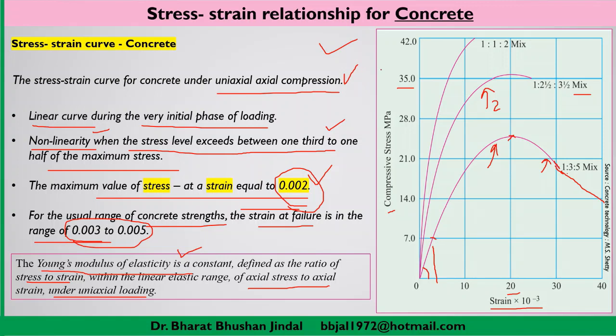So that means you are applying the load on the cube of the concrete just for 5 to 10 minutes, and you will be finding the failure of the concrete, and accordingly you will be calculating the compressive strength of the concrete.